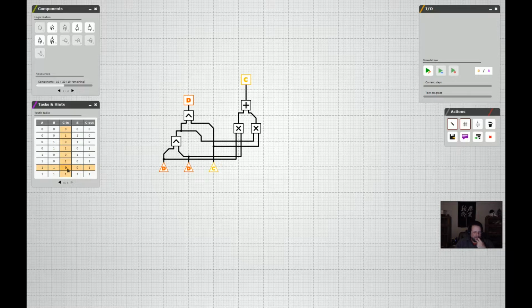Do we have that solved? In this one we have them both being 1s, the XOR. Oh, okay, we're taking them before the XOR. Of course we are. When A and B are 1s, down here, looks like any time A and B are a 1, no matter what the condition of C in, we're getting a 1 on C out. So that's why we can just take them from right here, put them into an AND gate, and have it go up to C.